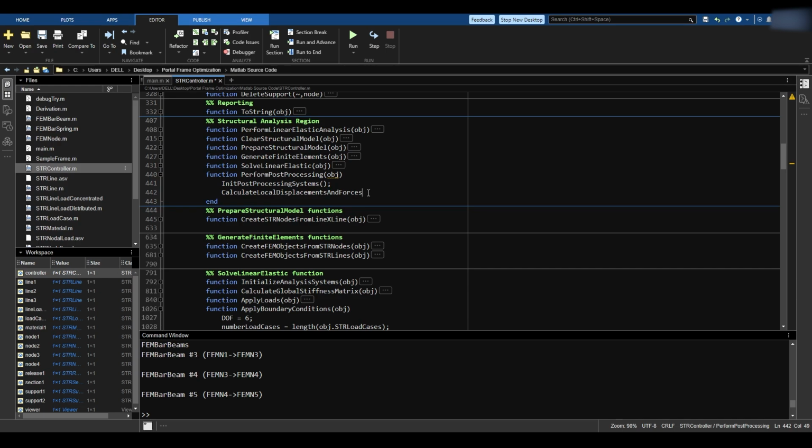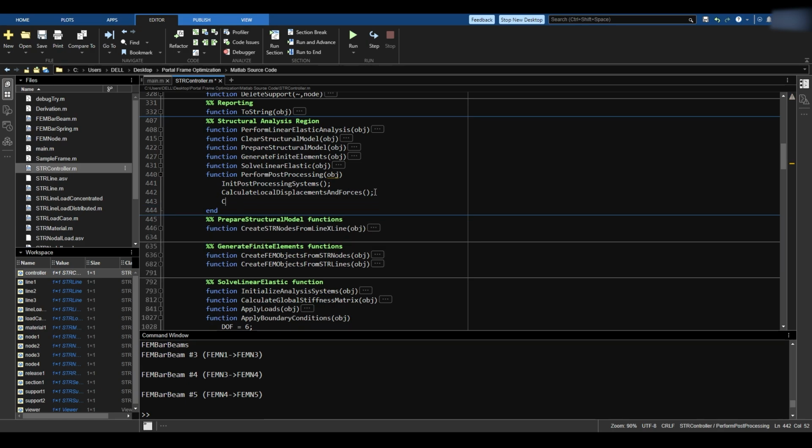In that case, I have the displacements of the nodes in the global sense, but I need, of course, to find the displacements in the local sense of the elements to find the forces in the local sense, because I want later to calculate bar internal forces and displacements. So in the end, my goal is to calculate the shear force diagrams and bending moment diagrams and all those cool diagrams for those elements once we're done.